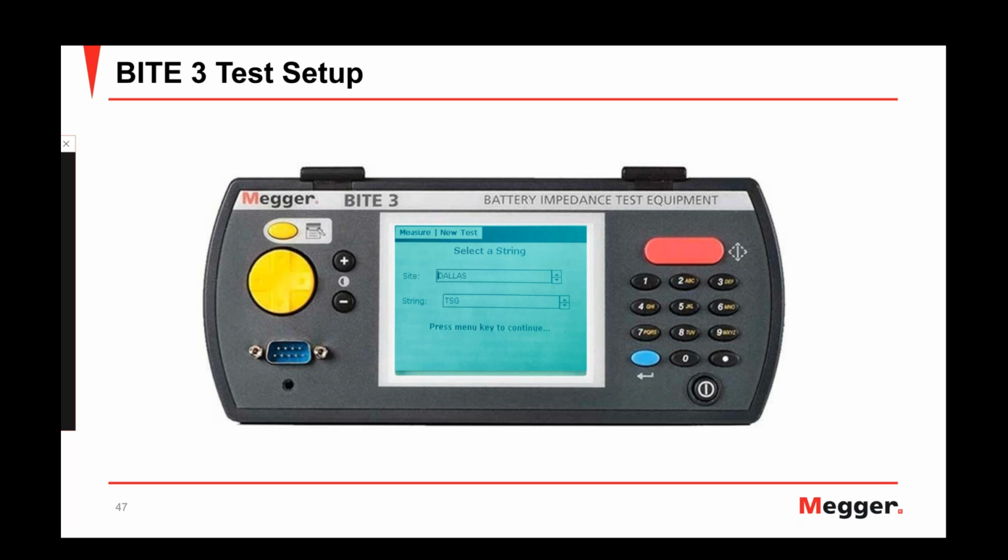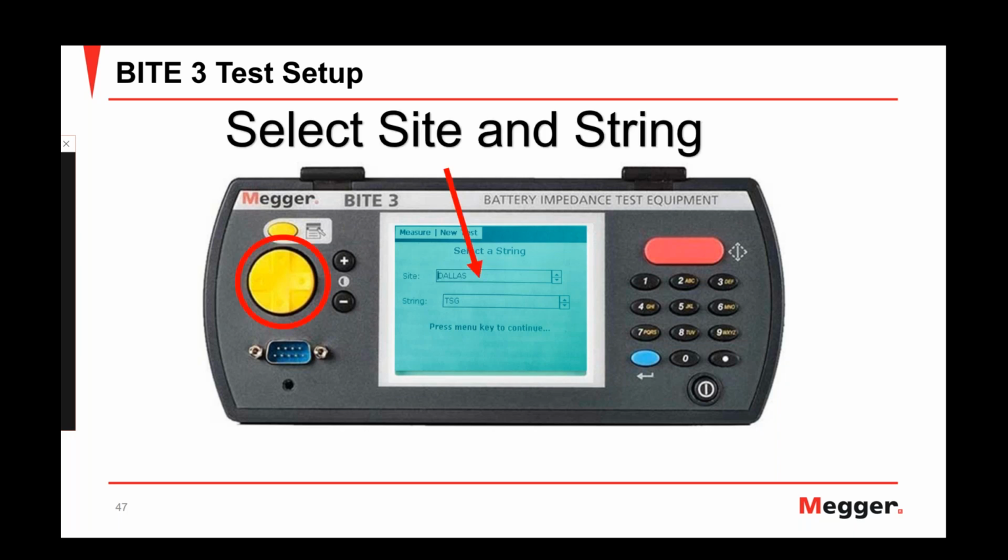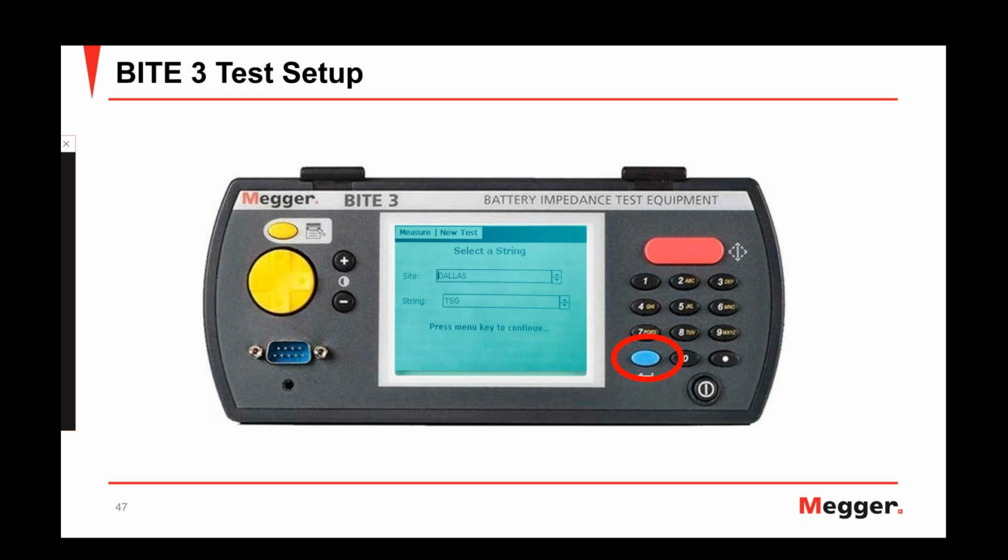So once you're in this prompt for the site and string, go ahead and use the yellow crosspad to select your site. And once you have selected the site, press the enter button and then select your string. Cycle through it in the same manner to select your string. Now, once you've done that, go ahead and press the yellow menu button, and it's going to ask you basically if you want to continue. So highlight, select, and continue, and press the enter button to proceed with the test.